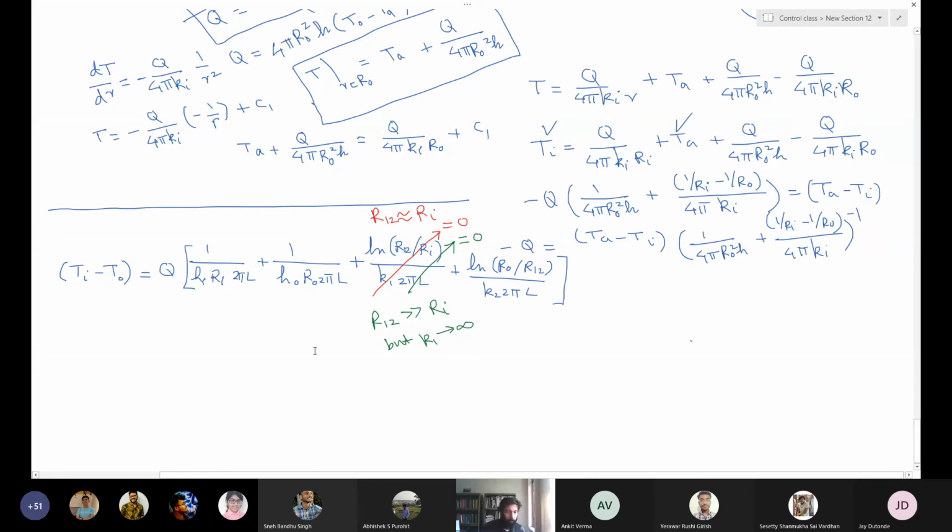Now let us elaborate a little bit on this point. Let us consider a pipe which is transferring heat to the outside. In many cases the outside heat transfer coefficient, Ho, is very small. That is because many times you are dependent on natural convection. For example, in a cold country, if you want to heat the room, you run steam through a pipe in the periphery of the room. You don't normally use a fan. By natural convection, the hot air goes up and heats the room. Inside you have flowing steam which has a very high heat transfer coefficient. Hi is very high, but Ho is very low.